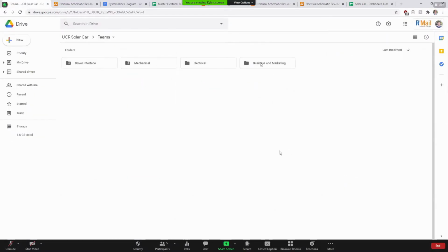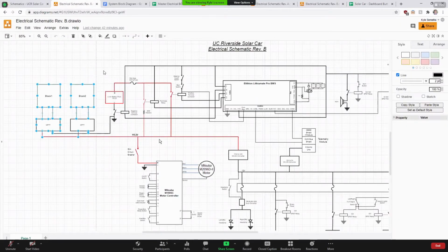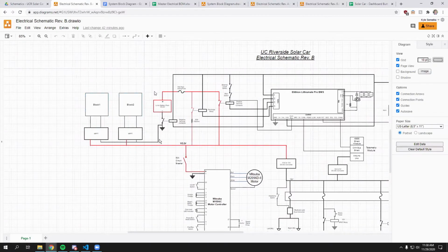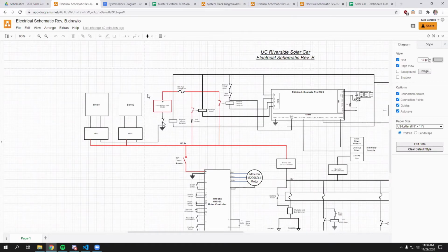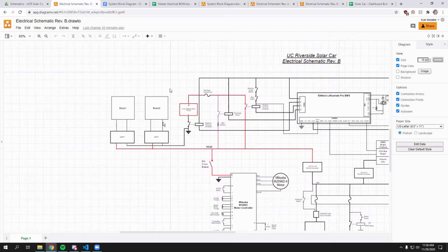I think I remember seeing the picture. Yeah. We have to come up with the wiring for the vehicle. First, we have to wire each sheet together. Second, we have to figure out where to place each bypass diode. And the bypass diodes go in between the sheets.